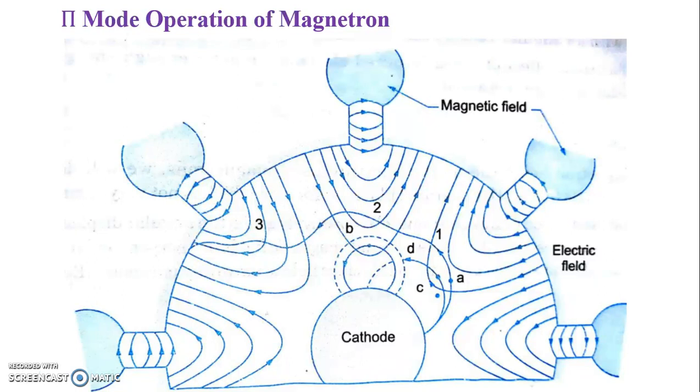An electron B is accelerated by the RF field, and instead of imparting energy to the oscillations, it takes energy from the oscillations, resulting in increased velocity. Hence, it bends more sharply, spends very little time in the interaction space, and is returned back to the cathode. Such electrons are called unfavored electrons, which do not participate in the bunching process. Rather, they are harmful because they cause back heating.